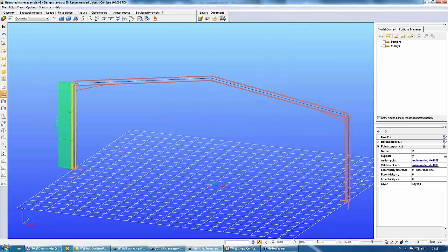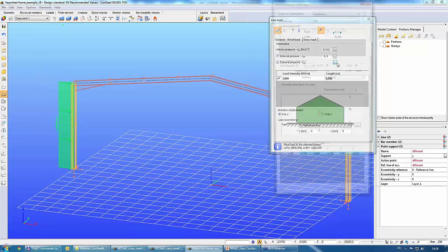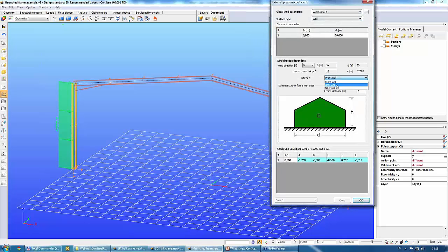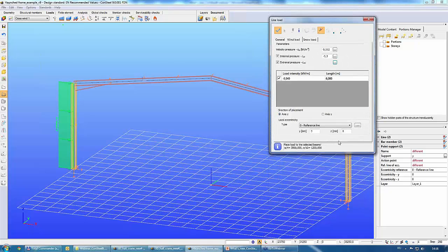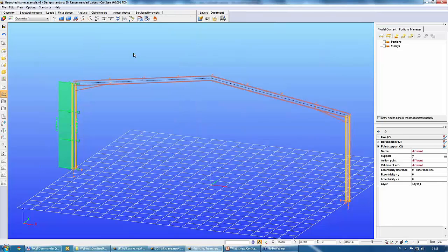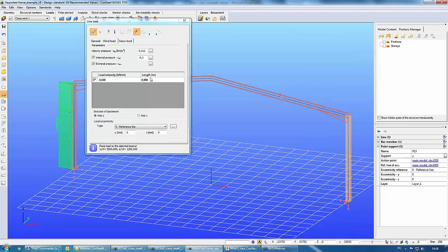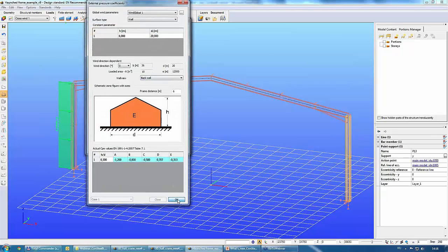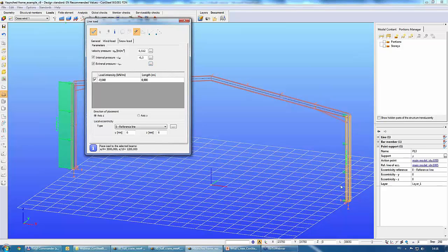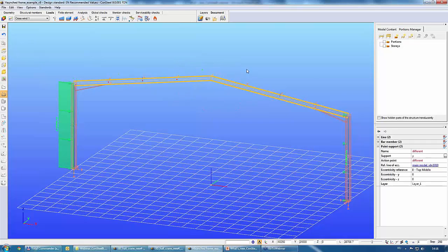Okay, we move to the other column. The procedure is the same, but it is not the front wall but back wall. Okay, and place. Sorry, I have selected 2 columns, so only this column. Back wall and place. And here is the load. Okay, and then select the whole roof, including 2 members together.